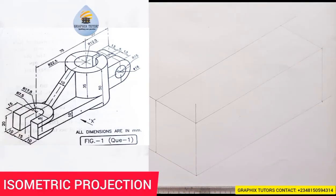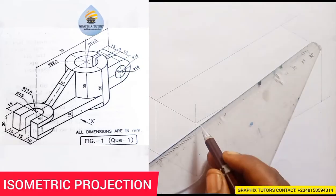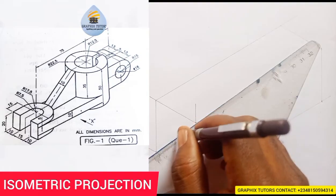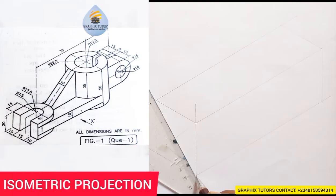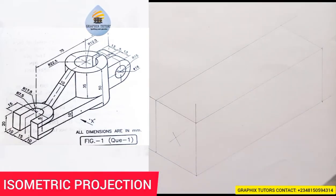And the next thing we're going to do is to draw this point here. So we should get the center of this figure, and it's easy to get the center. If you don't want to measure, what you should just do is join diagonals. So when I join this diagonal to this diagonal here, I'll just draw a line this way. I'll come here also and do the same thing, drawing another line this way. So where they meet will be the center of that figure. And when I take that point down this way,